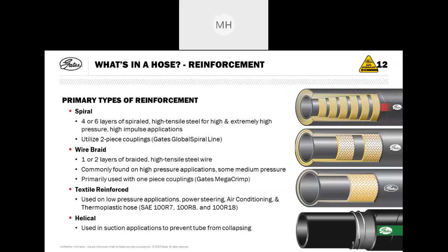And this is quite a good one because it comes up every so often when you're talking with people. What it's asking is about the layer of rubber between the 2 wire packs. So if you look down to the second image on the right-hand side, you'll see the inner tube, a layer of wire reinforcement, a layer of rubber again, and then the second layer of reinforcement. Now that there is actually a friction liner. It has no benefit for holding or assisting in holding any of the pressure or retaining the pressure from the tube. It's purely there to stop the 2 wires rubbing together.